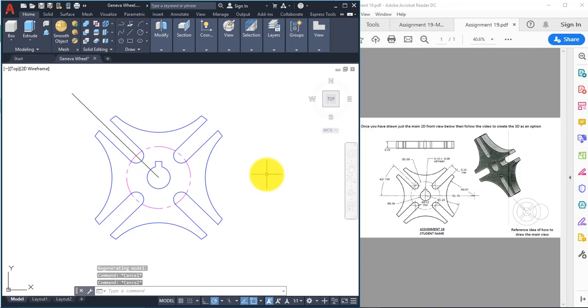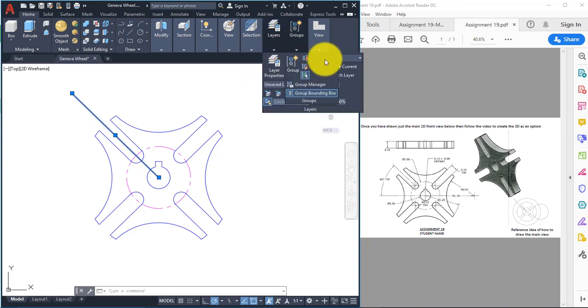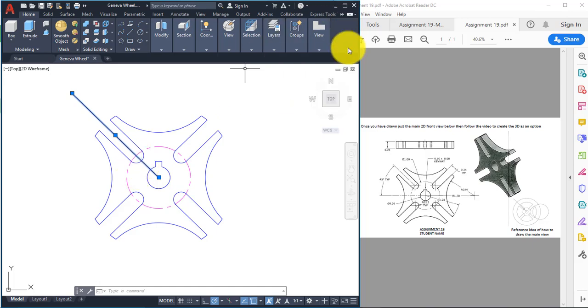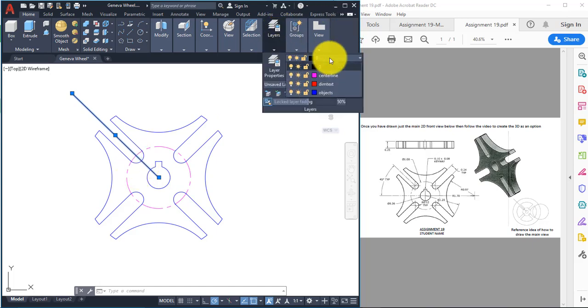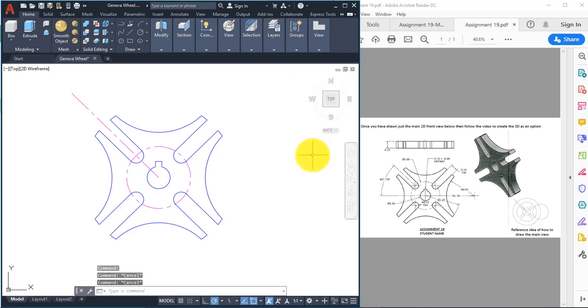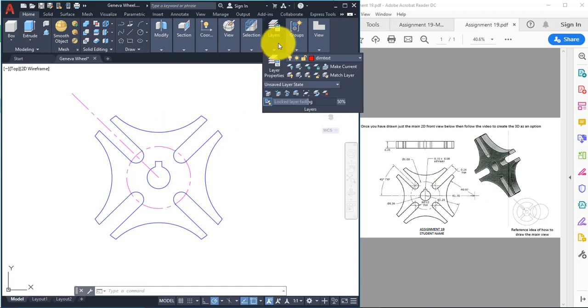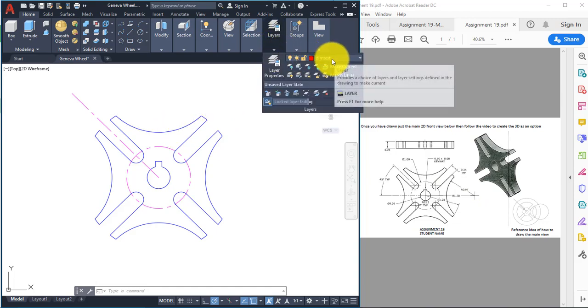Okay, also I believe this line right here in the drawing is center line. So I'll go ahead and go to the layer drop down. I'll select that line and go to the layer drop down and put it on the center line layer. There we go. Okay, so now we're ready to dimension. I did say in class that it's okay not to have exact dimensions like this. The first thing I want to make sure is the current layer is dim text.